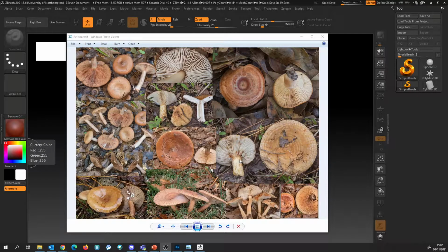Now what we're going to do as part of this process is sculpt the mushroom so that we can have some high resolution detail, such as strokes and the shaping that we want, and some of the spores that we have underneath that alignment as well. We're then going to manually retopologize it, and we're also going to project the detail onto a low resolution version of it, so that we'll have the high resolution used for the textures, and also the low resolution that we're going to use for a game ready object. So a few things that we're going to do.